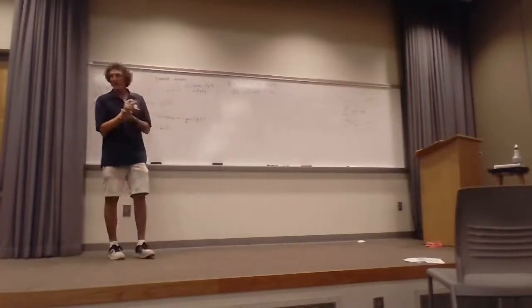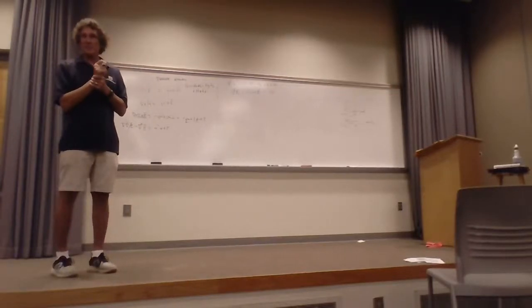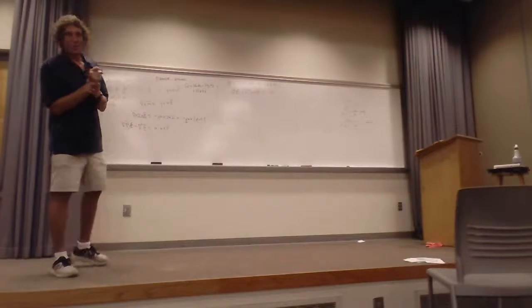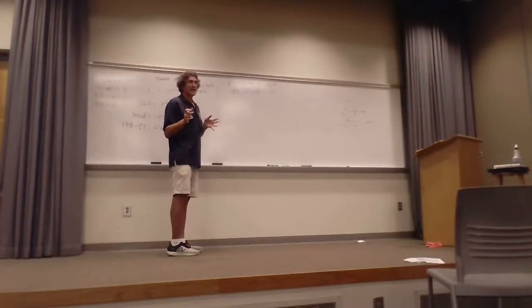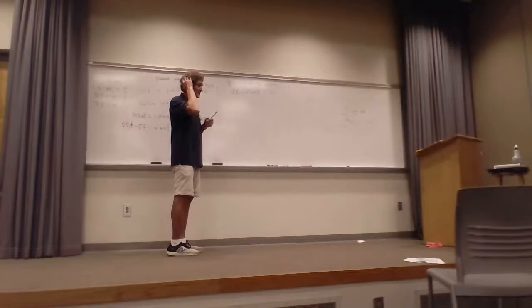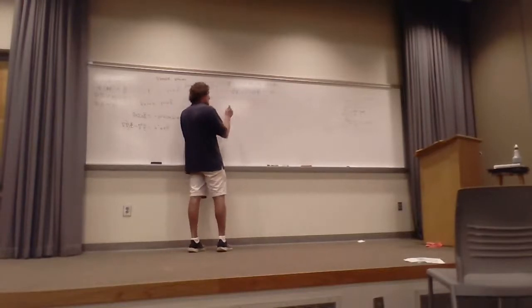All right, so there's really three field components to both E and H, in general. In order to make this doable, we're going to try to get these things down into some reasonable forms to solve. This is borne out with measurements and theory and everything like that. So the first assumption we make, write this down, this is going to be transverse magnetic.